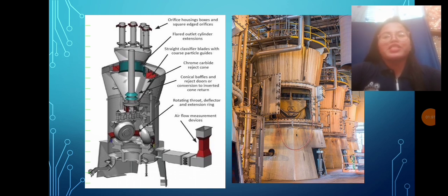Pulverization of coal basically breaks the big coal lumps and increases the furnace surface area, which is important to facilitate efficient burning of coal. So if the coal is not pulverized, the coal might not burn completely, resulting in a waste of fuel. Also, pulverization of coal helps the boiler respond to load variation more promptly.